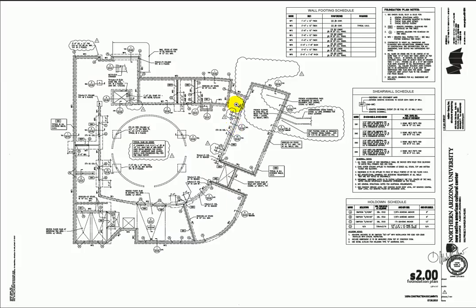So now I have a good feel that there are little strip footings around the perimeter. Remember from the general notes they had to be 2'6" below the exterior grade or the finished slab. In this case the exterior grade was lower. So that tells the contractor how deep to go. You'll note on the drawings it didn't give any elevations, which puts a lot on the contractor to figure out.